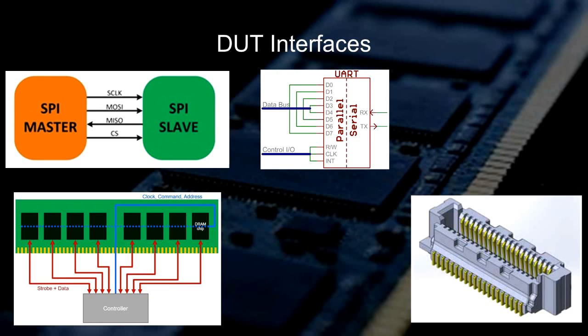There are three memory devices that were integral for this project, those being the SPI NOR flash, the NAND flash, and the DDR4 memory part. Beginning with the NOR flash, it'll be communicated with over SPI communication via high-speed COM ports set up in EMIO configuration. Next, moving on to the NAND flash, that'll be parallel communication via high-speed GPIO pins. And finally, the DDR will be communicated with through the MIG interface on the Zynq UltraScale+ FPGA chip.